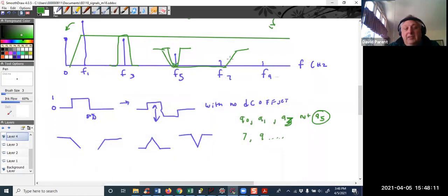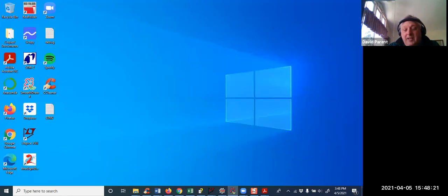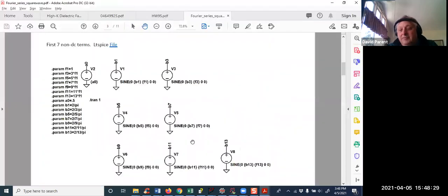So what I can do is take a square wave and then select the ones I want and then amplify them and maybe attenuate them to where I can get something that sounds like a piano, and that would be additive signal synthesis.